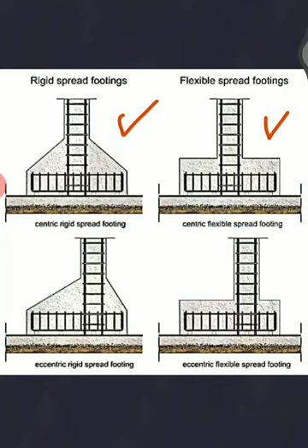Now there are three basic things in a column. You will have a footing portion, then you will have the column base. Over this column base you will have the regular column. So three different things will be there, and you are supposed to find the reinforcement of the mesh. This we call the mesh. This is the hook mesh or column mesh. Then you will have spliced bars which will run from the column base to the footing.